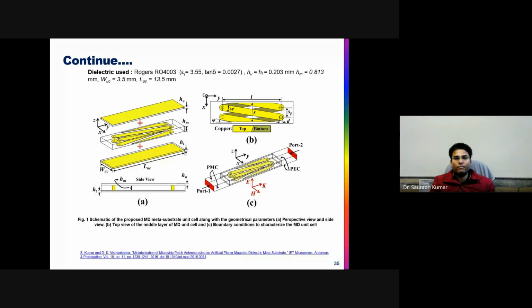You have your planar structure, meaning through the via you have created your split rings such that they can be excited with the electric and magnetic field, or with the magnetic field of your antenna only. As you know, this is the complementary split ring, and it is excited with the magnetic field that is perpendicular to the surface of the ring.